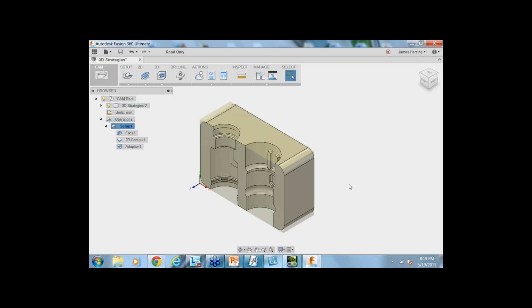machining operation. For that operation alone, and then the rest of them, for us to clean this up would take a bunch more time. Significant time, yes. Longer tools like that, especially ball mills, need to be run at about a third of what a square-ended mill would be. Oh, okay. So this is good to know. It scares me again to even think about going and making something, but all right.